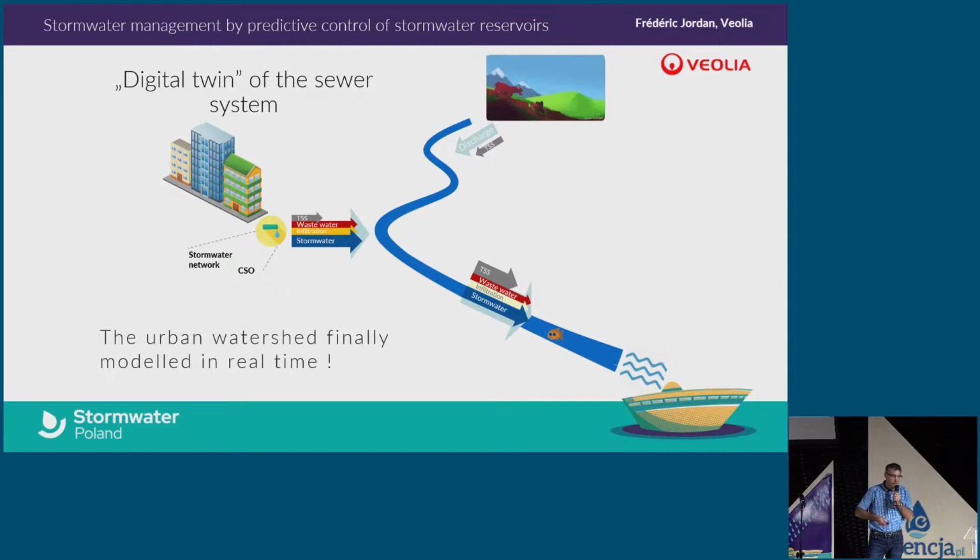Then we will model, in a very classical rainfall runoff simulation, the urban hydrology: runoff water, infiltrated water, wastewater, including also the polluting fraction, parasite water, infiltrated water, ammonium. And then we can also model in the same way the final concentrations in the natural environment, so in the river or in the lakes.